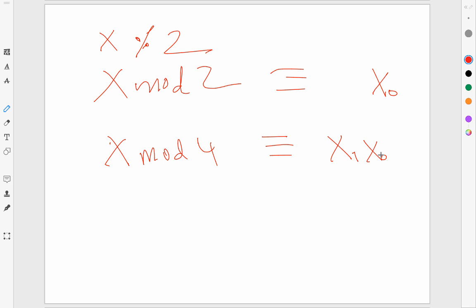So the encoder example. Firstly, anytime some input is invalid, then that's don't care. In this example, the little encoder really can only see two types of valid inputs, all zeros or a single one. Anything else is invalid, not just for this little encoder, but for whatever bigger encoder we are trying to make of it.